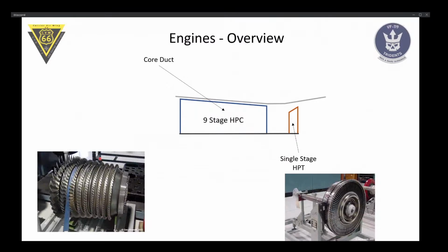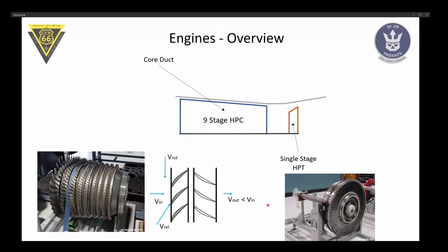Here, a bit more naturalistic depiction. This is a picture, I think, of the actual compressor of the F-110. You can see it has little blades that turn and compress the air, and these get progressively smaller because the air is getting compressed and loses volume, so the channel has to constrict itself. On the other side, you have the turbine. Not much to see here, unfortunately, because the shroud is welded on the blades, so you can see the blades, but it's basically a similar concept, reversed.